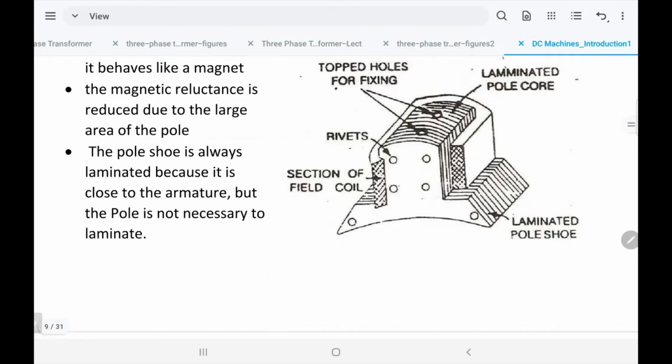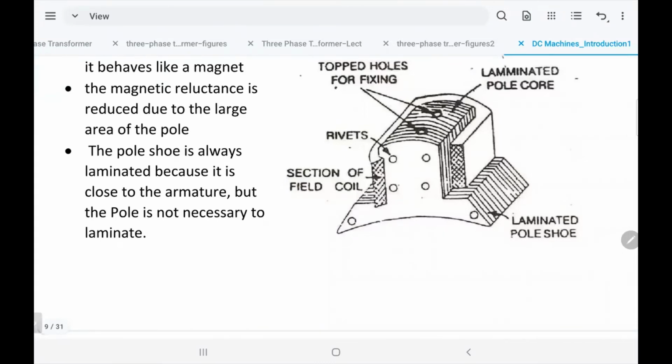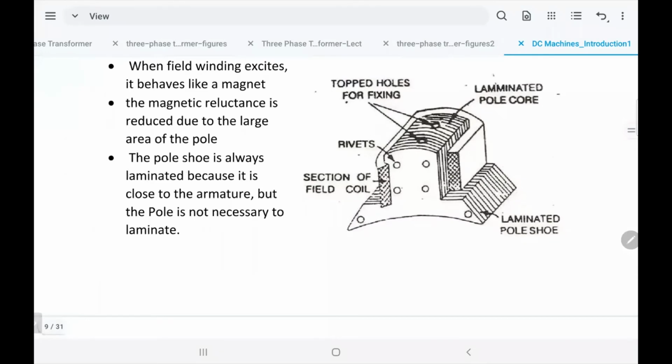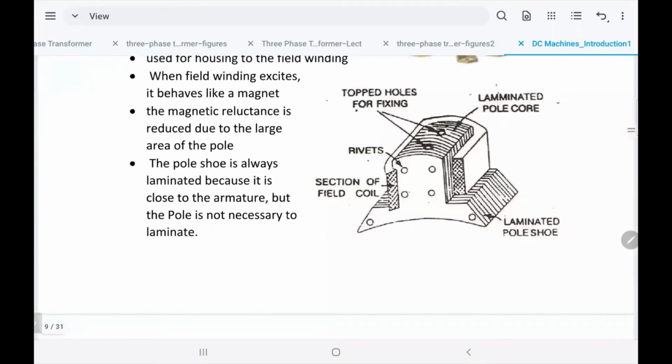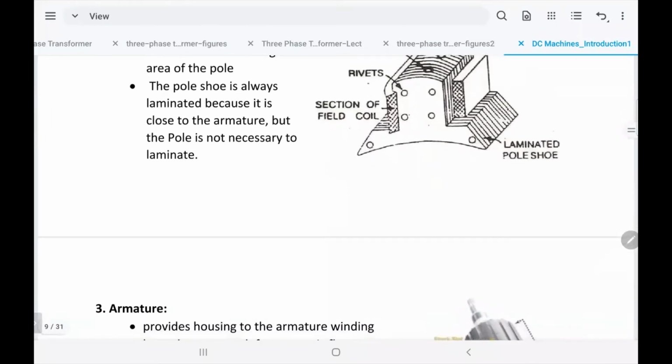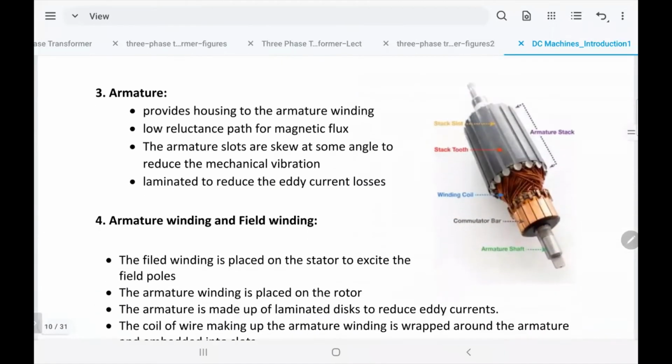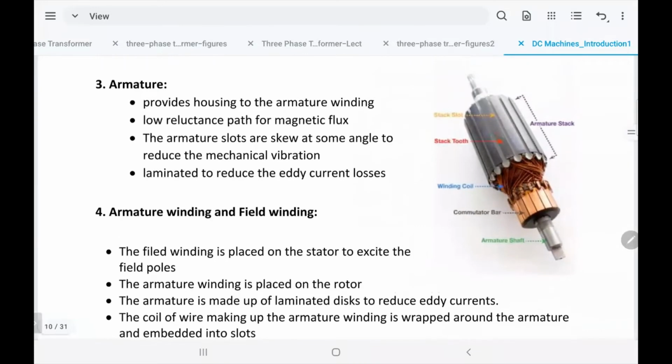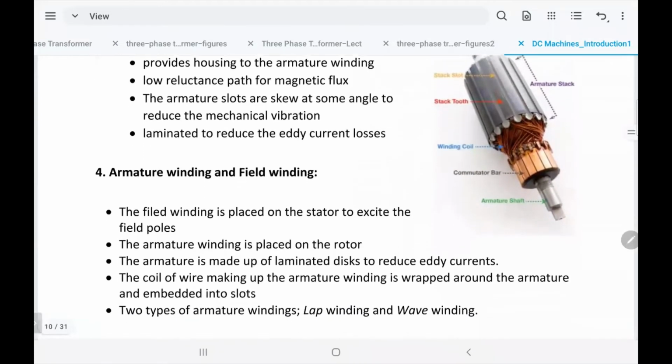We will have a magnetic field, and the magnetic field produces electric eddy currents, which circulate inside the iron core. So they make it from very thin pieces of metal to minimize the eddy currents. And that's the pole where they have the wiring around it. We'll do some calculations for this one, but this is the way they put their field winding.